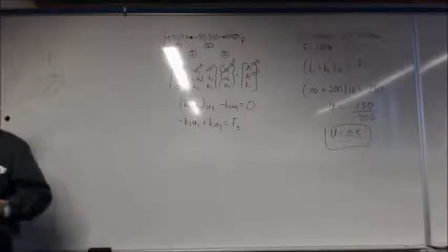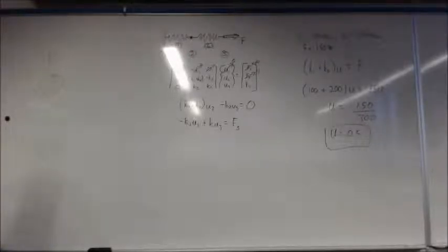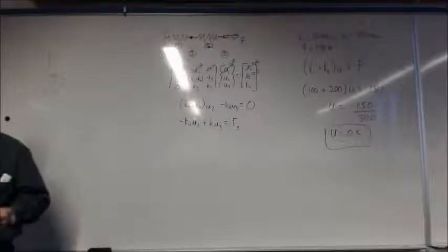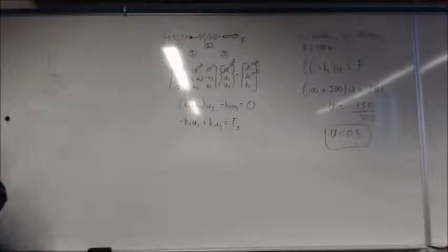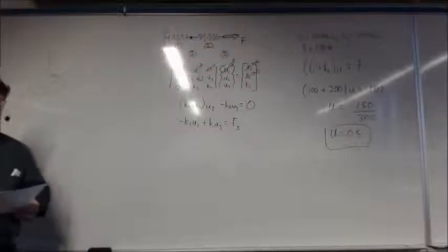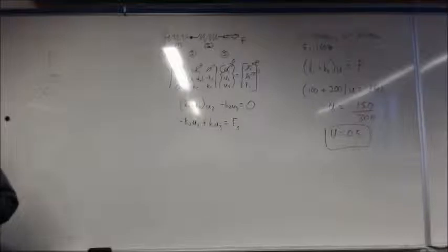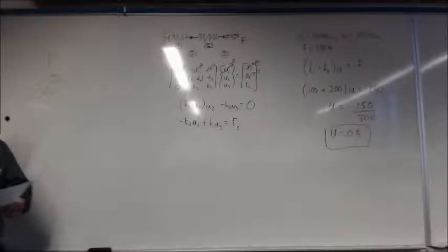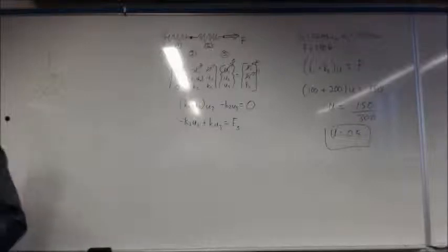Okay, so one of the assumptions made when we use a truss element in a model is: A, the connections can resist the moment. Well, that's false. B, the element can be subdivided. That's false. C, there's no kinematic collapse. That's true. And D, cross-sectional changes are allowed between connections. That's false, right? So the answer is C.